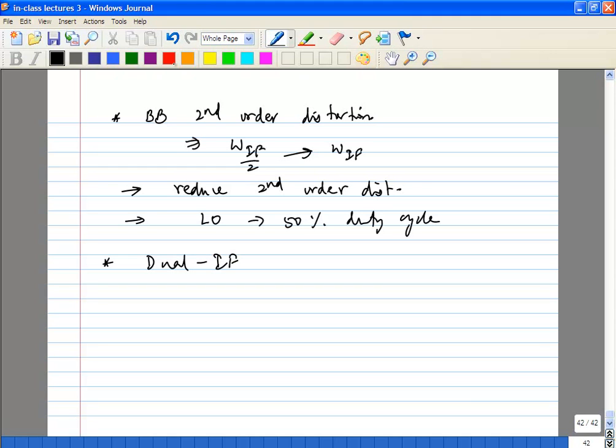Now this is actually a single IF superheterodyne, so single IF heterodyne. You can actually have a dual IF or a triple IF also. So instead of having a single IF, you can have multiple IFs. You can go down to a certain frequency, do a little bit of filtering, a little bit of gain, and so on, and keep doing that. What happens is you are basically distributing your filtering over multiple IFs. So the filtering requirements for each IF are reduced, right?